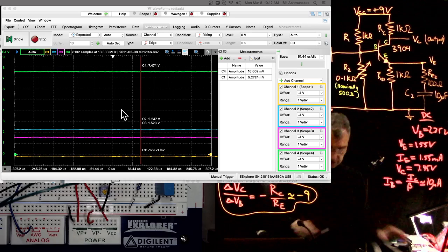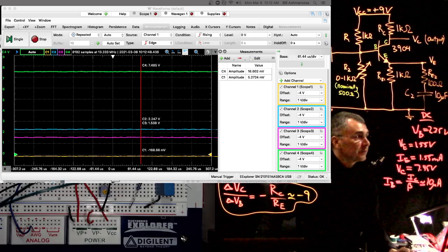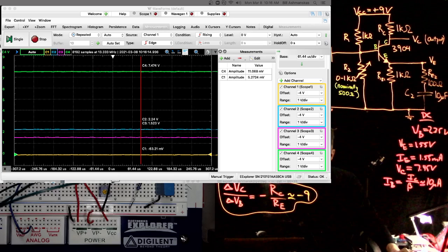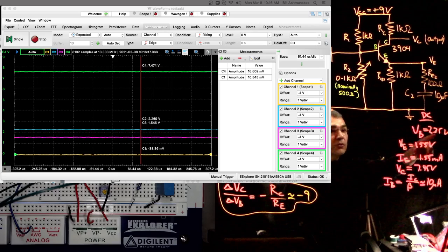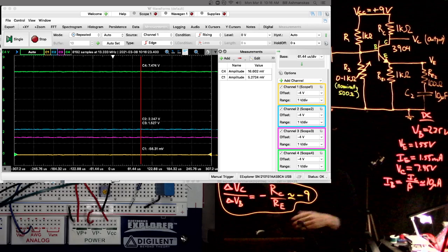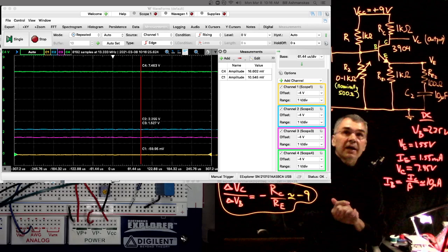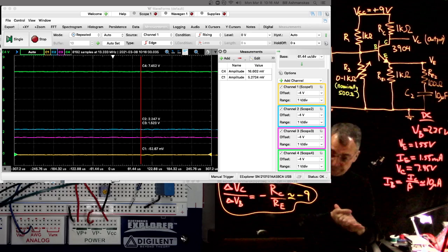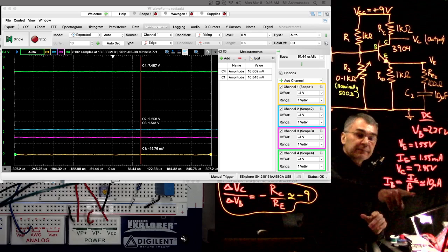Let me just estimate what that is. So I worked out that in order for V base to be 2.25 volts, we must have set R2 to be about 333 ohms. And then R1 parallel R2 is about 250 ohms. And then you multiply that by this base current of 10 microamps estimated.